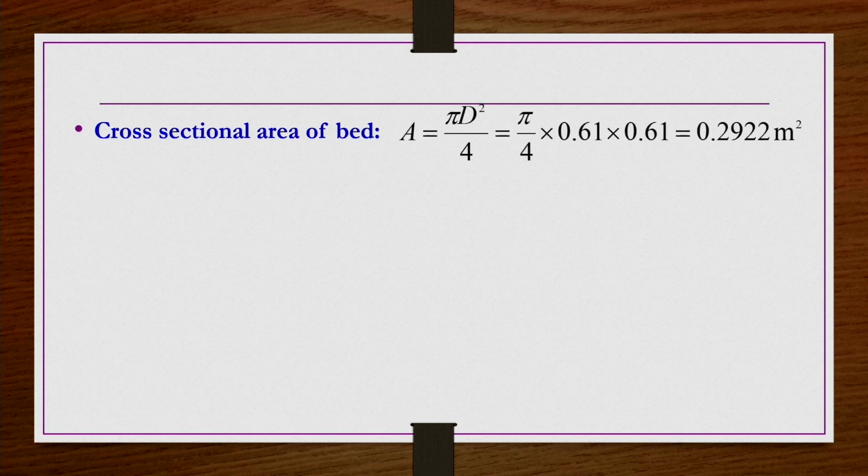Very simple: you have to find out the Reynolds number first of all, whether it is in the small flow region or the high flow region, so that you can use only that particular part. In order to know the Reynolds number, you need to know the superficial velocity, V naught bar, but it is not given, rather the mass flow rate is given.